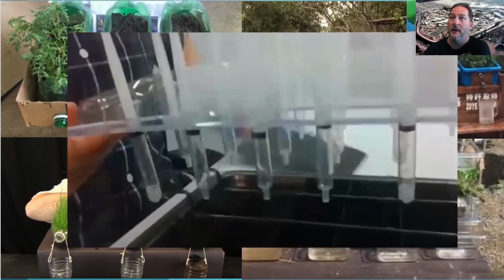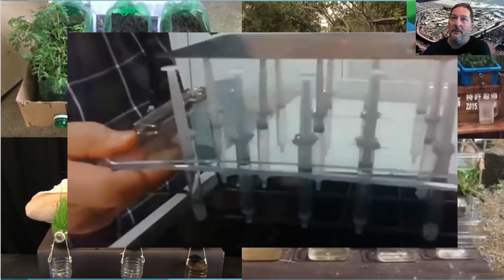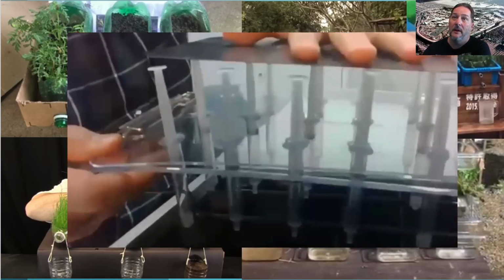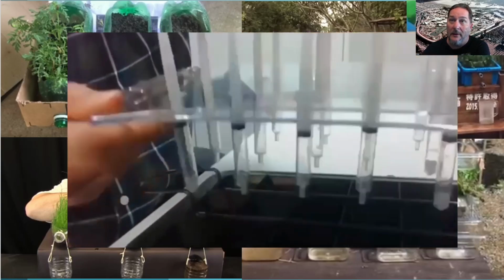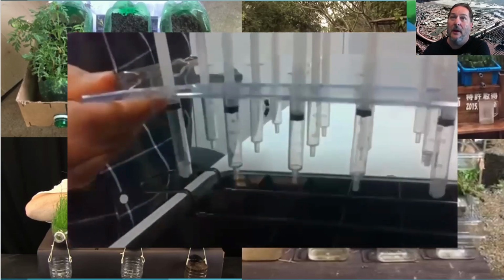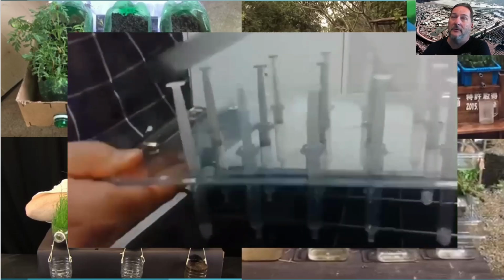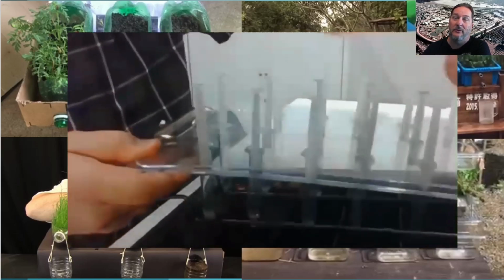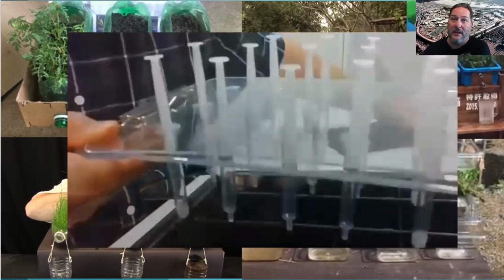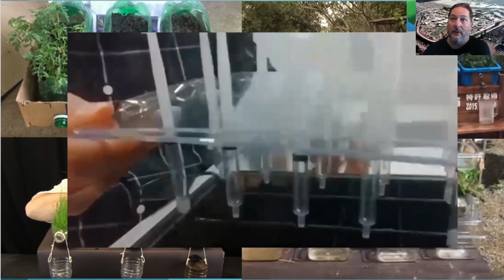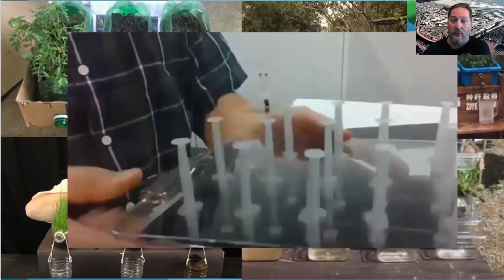Now it could be the same if I take this plate here and put it on the top of it and vary the tempo but not the slope of it. That is your temporal hyetograph, your temporal pattern. But what you could also do then with spatially varying rainfall is change the angle of attack. And then that storm could come through with a different hyetograph for every single one of the computational grid cells.